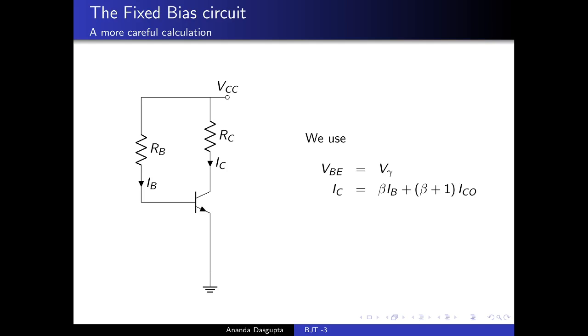So that's exactly why we do this. We just use a single battery to drive the circuit. So we are connecting the single battery via RB, the base resistance, to the base, and via RC, the collector resistance, to the collector. And the emitter, of course, is grounded.